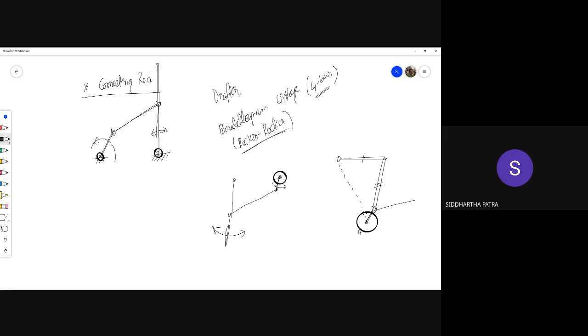And you need to understand why the pedal must be this small. Because the pedal is small, the pedal acts like a crank, and this portion of your body, and also this portion, becomes a rocker. So this basically oscillates. From your hip to your knee, that one only oscillates. That doesn't go full rotation. And this crank goes full rotation and makes the cycle move forward. Okay, and this portion is called a coupler, which basically couples between the crank and the rocker. So this one is the crank, the pedal, and your thigh becomes the rocker. Okay.